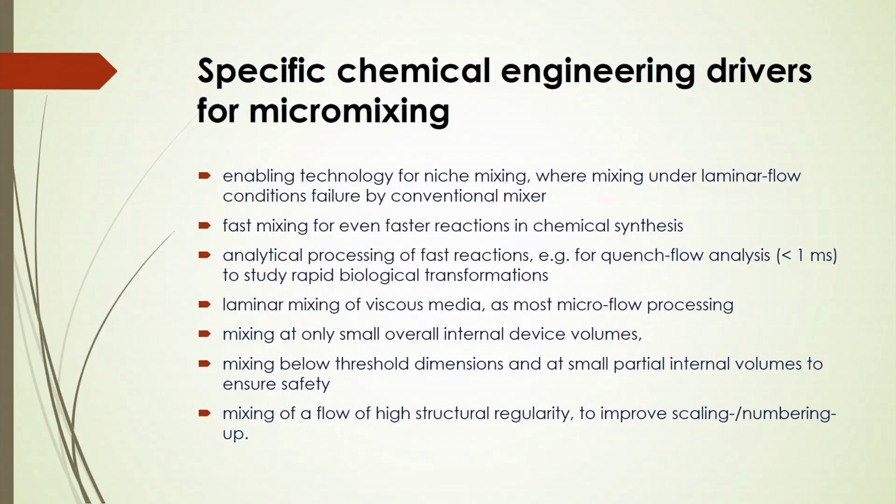Now, specific chemical engineering drivers for micro mixing: it enables mixing under laminar flow conditions, which is valued over conventional mixers. It also gives you fast mixing for even faster reactions in chemical synthesis, mixing at only small overall internal device volumes, and mixing of a flow of high structural regularity, where you can also improve scaling and numbering up.